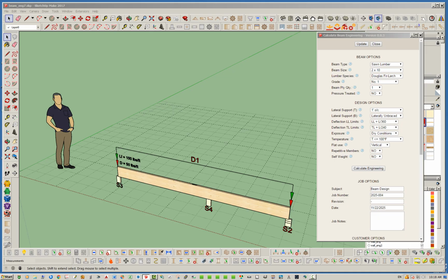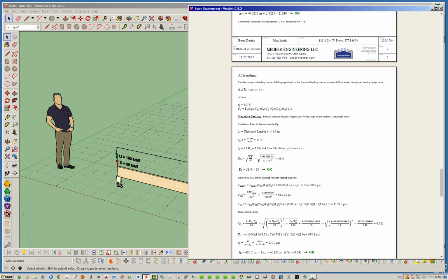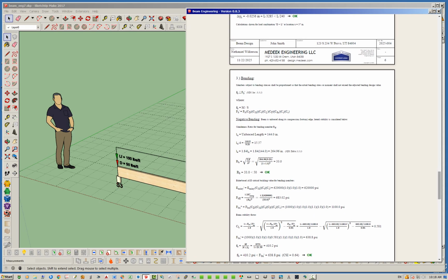Let's put it this way. At a very minimum, I think you need to have 2 brace supports at the ends of the beam. Otherwise, the beam is just going to flop over. If you ever framed up a floor in construction, you'll notice that until you got those joists framed up and the tails tacked into the rim joists, the joist is going to flop over. So again, we have to make that assumption that the 2 outermost supports are secured and braced both top and bottom.